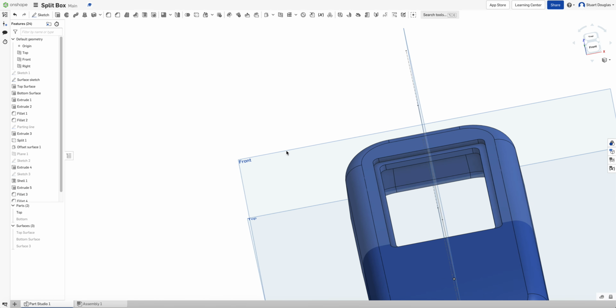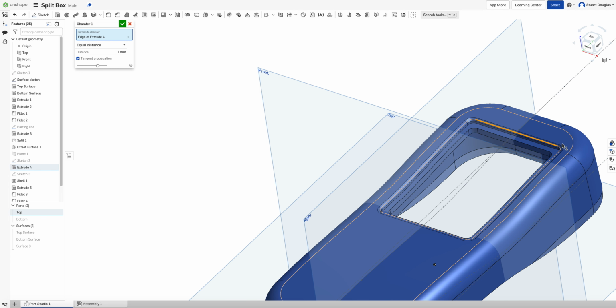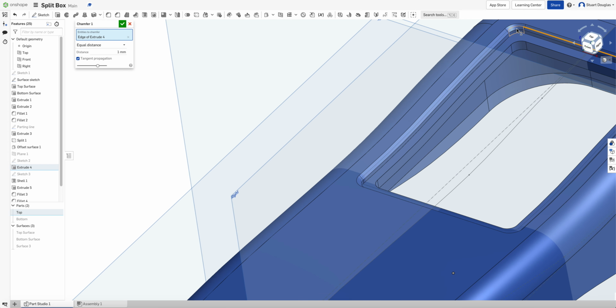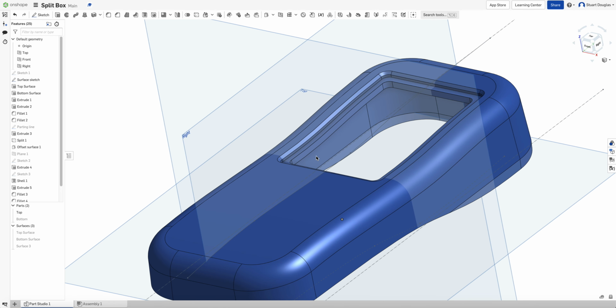And the last thing we're going to do on this, just to make it look a little bit nicer, is we're going to add a chamfer, which is this one. So a chamfer is typically a 45-degree angle. We want to change that measurement to be 1 to begin with. And we're going to pick that outer edge. And because we put the rounds on, it now sees that as a continuous loop. Therefore, it's actually applied a chamfer all the way around, which is great. And that's exactly what I wanted.